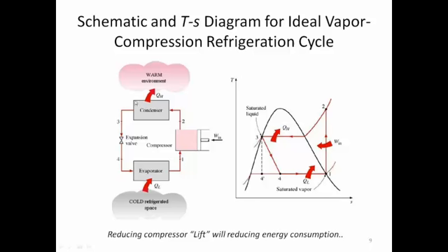Some people like to look at sort of a block diagram, schematic of what's going on, and others like to look at sort of the enthalpy diagrams. But the point is that in this refrigeration cycle of compress, condense, expand, evaporate, etc., this cycle that goes on in all heat pump-based systems, whether it's a DX unit or a chiller unit or your refrigerator in your kitchen, it doesn't matter.